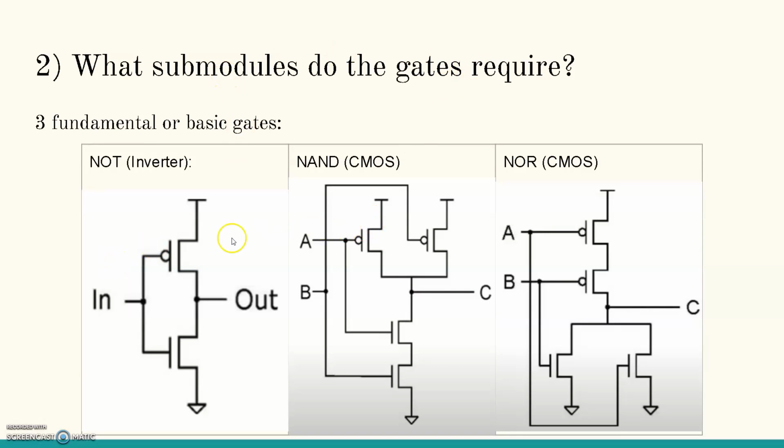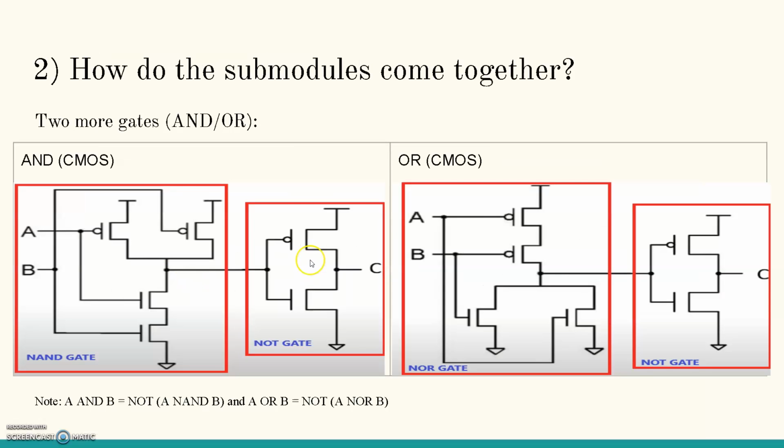And so in terms of how you would put the MOSFETs together, they're always in a CMOS complementary fashion. In fact, the NAND here, it has the PMOS in parallel and then the NMOS in series, and it's always like this. When NMOS is in series, PMOS is in parallel. When NMOS is in parallel, PMOS is in series. And so this is just how it should look in terms of the schematic. I'll explain more how this operates.